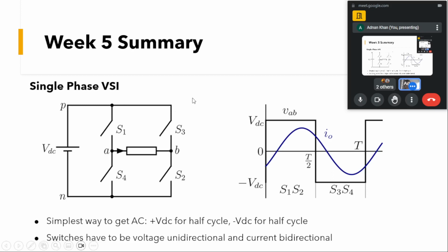So you saw here, due to this topology, it resembles an H. That's why we call it an H bridge as well. So with the DC source and H bridge, we are able to generate the simplest of ACs, a plus VDC and a minus VDC, that is kind of a square wave. You can see here, this is the simplest of the waveforms that we could generate.